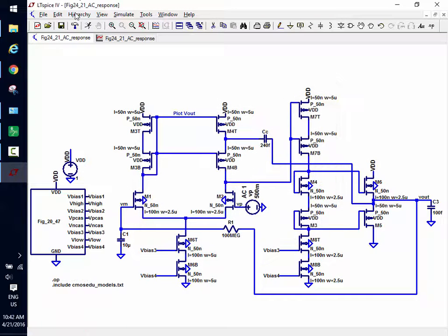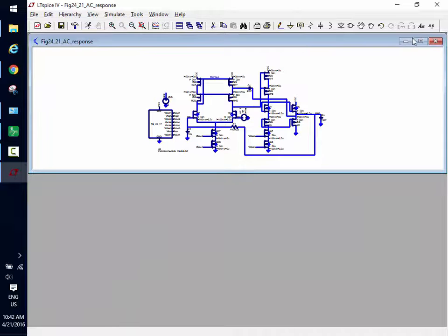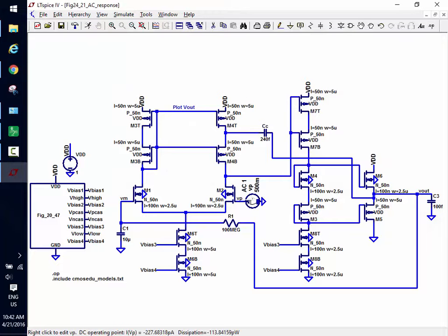Run. So this is 0.5 volts. Oh wait, something's wrong here. 150, 100, oh. Does everybody see the issue? When I copied, my L was 100, but when I split these up, I used 50s. So here I have a 50, here I have a 50, and I need hundreds.